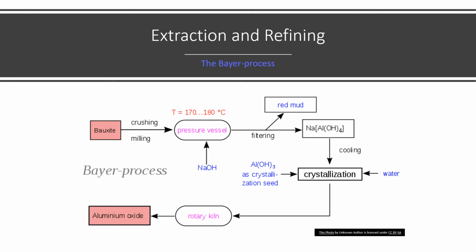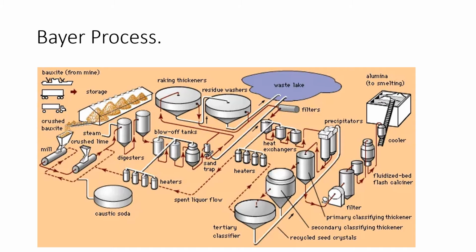Purified alumina usually contains 0.5 to 1% water, 0.3 to 0.5% soda, and less than 0.1% other oxides. The Bayer process, with various modifications, is the most widely used method for the production of alumina, and all aluminum is produced from alumina using the Hall-Héroult electrolytic process. The Bayer process involves 4 steps: digestion, clarification, precipitation, and calcination.